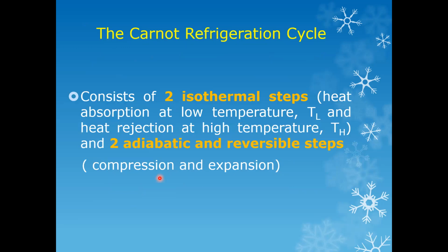Next, we discuss the Carnot refrigeration cycle. It consists of two isothermal steps: heat absorption at low temperature and heat rejection at high temperature. So just like our Carnot engine cycle, but in the opposite direction. And also two adiabatic and reversible steps, the compression and expansion steps.